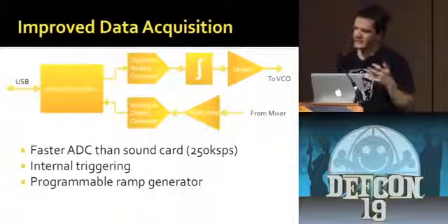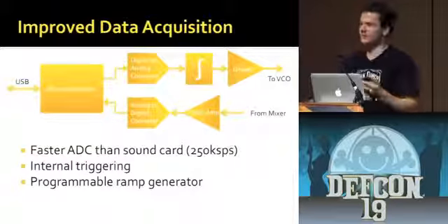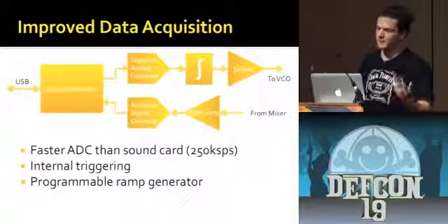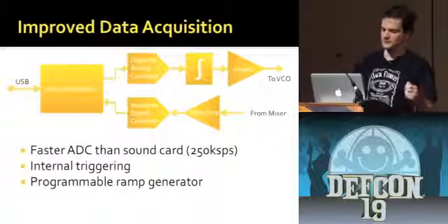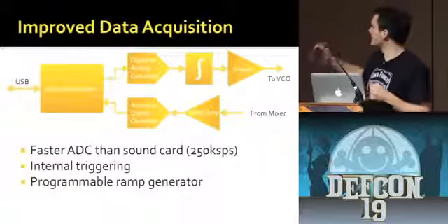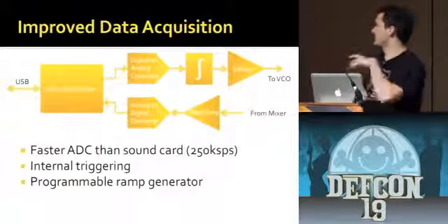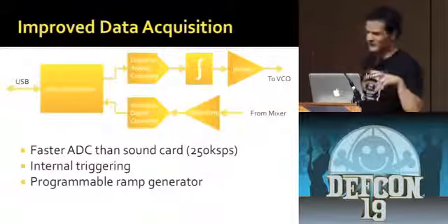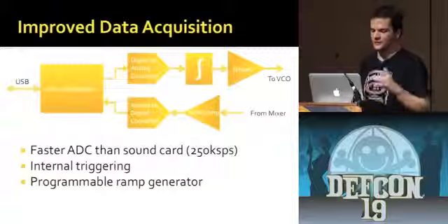So we could filter the hell out of it and it probably wouldn't work, or we could just generate a flat signal and then in analog make the ramp. That was the easiest option, and it works pretty well. And then we just send that out to the VCO. On the receive side, we have a video amp. That was actually not on the green board, it's on the other board there. And then there's an A to D converter, which is way faster than the other one.